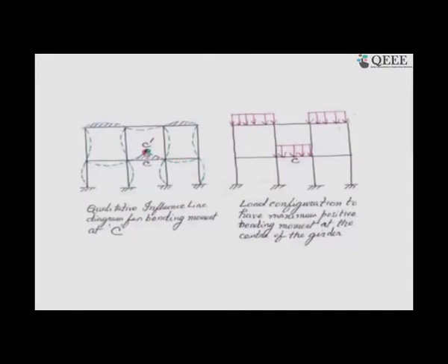Two rigid bodies, one is here, another is here, connected by an internal hinge, and that is how it will not resist bending moment this way. Of course, the muscles can resist the bending moment, I can become stiff. So, the stiffness of this beam can be increased, and if somebody applies load, he will feel some resistance. But without that, with my hand, it is just a release like an internal hinge. So, here an internal hinge is formed.